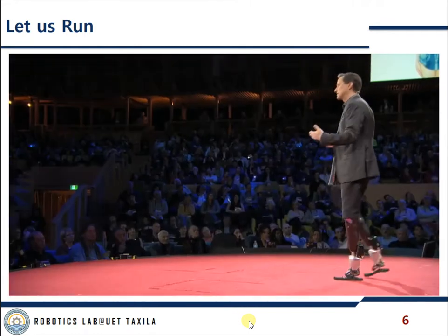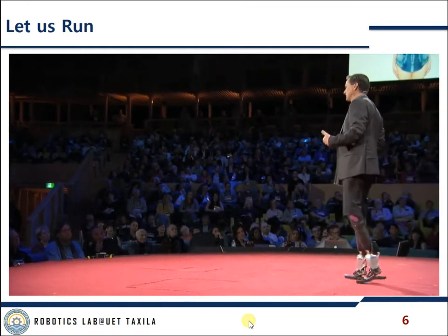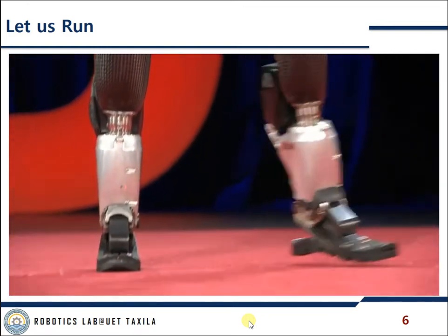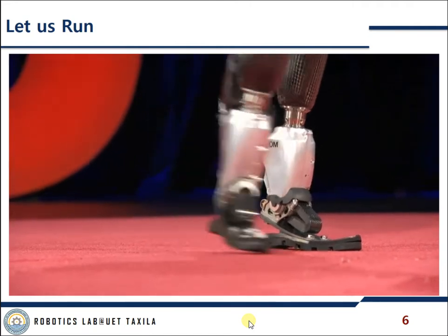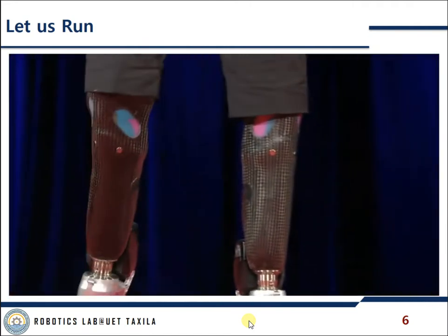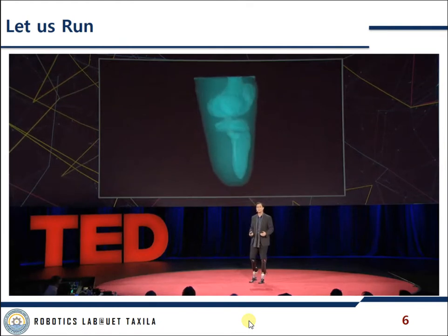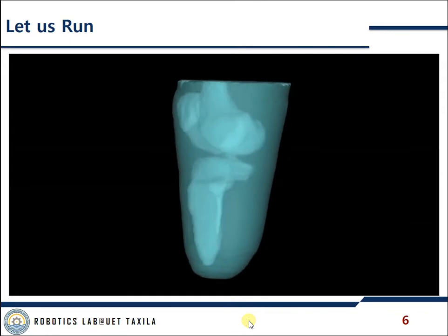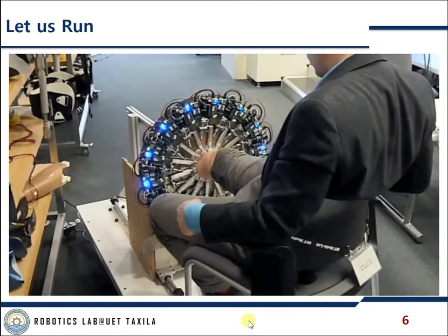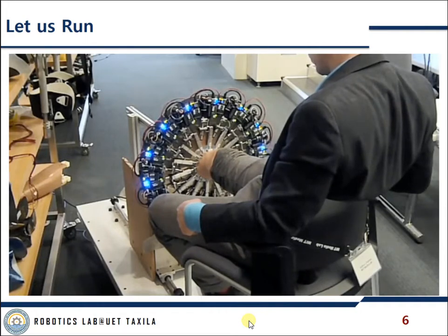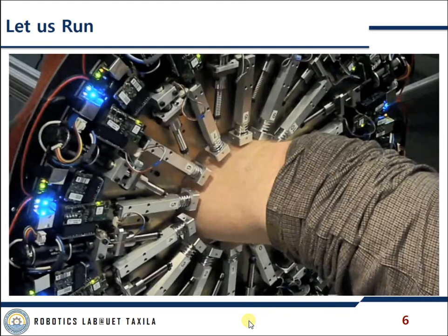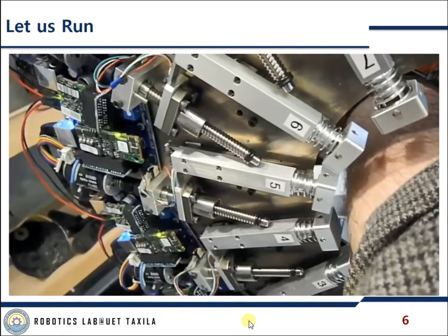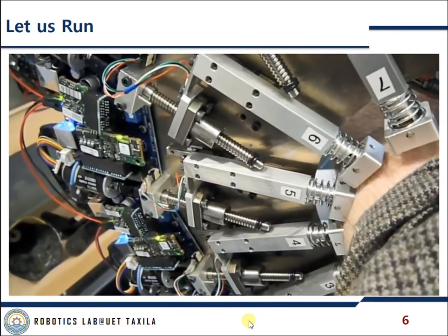My bionic limbs are attached to my biological body via synthetic skins with stiffness variations that mirror my underlying tissue biomechanics. To achieve that mirroring, we first developed a mathematical model of my biological limb. To that end, we use imaging tools such as MRI to look inside my body to figure out the geometries and locations of various tissues. We also took robotic tools. Here's a 14-actuator circle that goes around the biological limb. The actuators come in, find the surface of the limb, measure its unloaded shape, and then they push on the tissues to measure tissue compliances at each anatomical point.